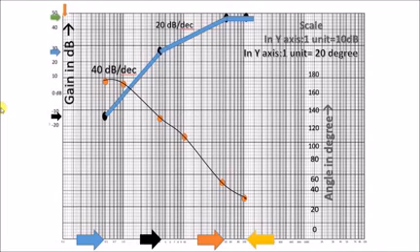So what is gain margin? The extra amount of gain which you can use without the system going on the verge of instability. So that much k value. What k value can you adjust so that the system is in a stable state? After that, the system becomes unstable. Similarly, phase margin: what angle value can you change so that the system will be stable? After that, it will become unstable. So those are called phase margin and gain margin.